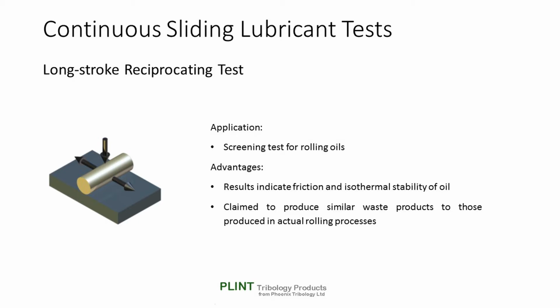In rolling processes, the same lubricant is used throughout the different stations, and temperatures and pressures vary throughout the rolling train. As different chemicals react differently at different temperatures, the lubricant additive package must provide consistent performance in friction reduction, wear prevention, etc., over a range of temperatures.